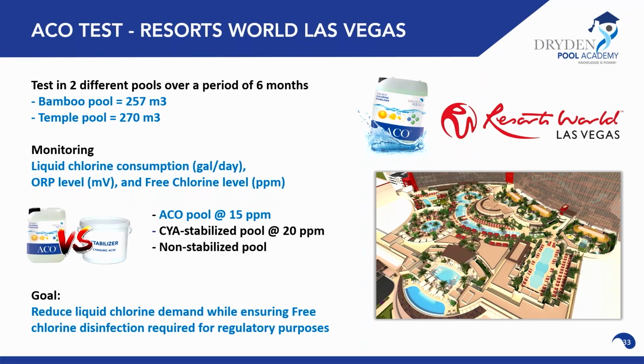You want to take this? Sure. The 2 pools we have are the bamboo pool at more or less 260 meters cubed, and the temple pool at 270 meters cubed. What we're looking at is monitoring the chlorine consumption in gallons per day, the ORP and the free chlorine levels. Here we're using ACO at 50 milligrams per litre, the cyanuric acid stabilised pool at 20 milligrams per litre, and of course the non-stabilised pool.